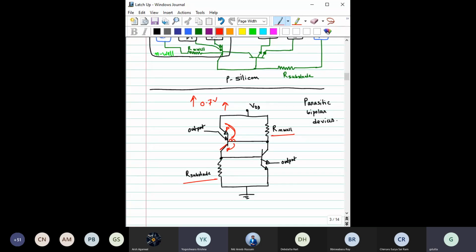These two terminals are already reverse biased, right? So what we have to do is, momentarily, for some time, just forward bias this. If we are able to forward bias this region, then what will happen to the collector current, say IC1? IC1 will increase. If IC1 increases, what will happen to this IE1? IE1 will also increase. If IE1 increases, what will happen?